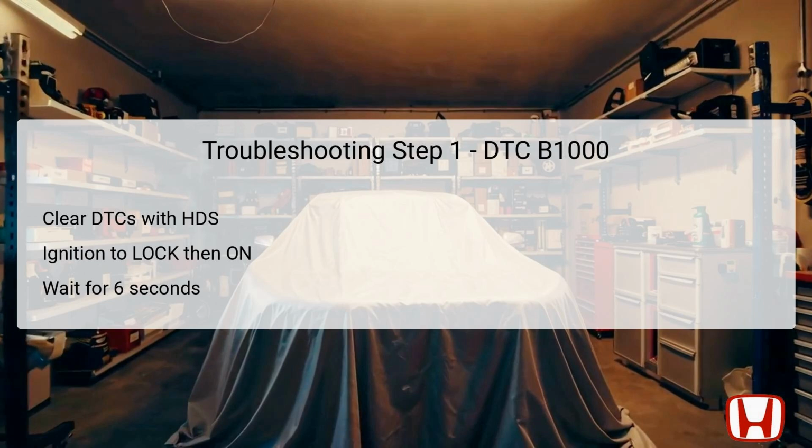It's important to wait for at least 6 seconds after turning the ignition on to allow the control modules time to initialize and communicate properly. This step is crucial as it resets the DTCs and helps determine whether the error is persistent or an intermittent issue. When complete, the technician can check for the presence of DTCs again with the HDS to continue the diagnostic